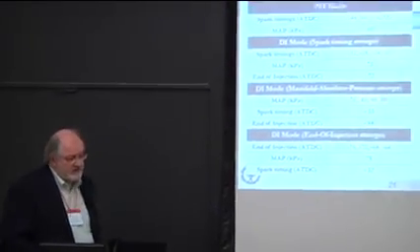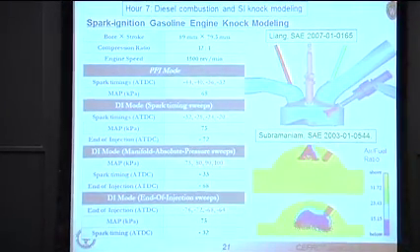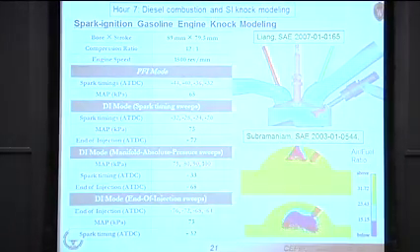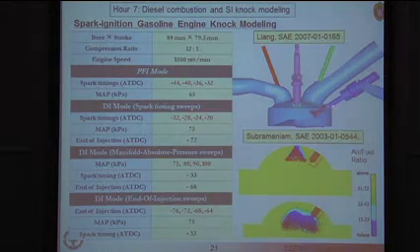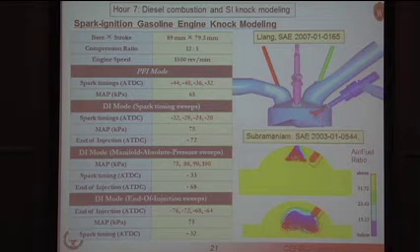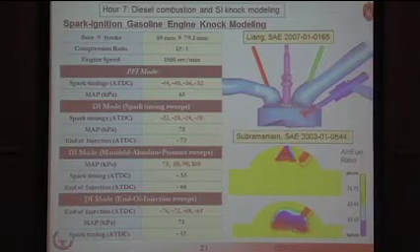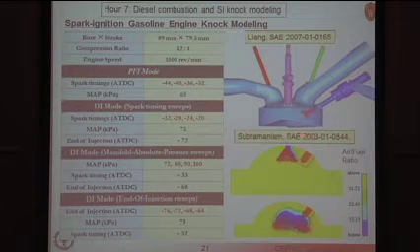And what I want to talk about now, briefly, is spark ignition engines, because spark ignition engines are also premixed combustion when we have port fuel injection, but stratified combustion when we have direct injection, like in the examples shown here. So here's your spark plug, here's your fuel injector, you inject fuel. Sometimes it's redirected by the piston geometry. Sometimes you spray directly at a spark plug. In other cases, you use the piston to move the fuel to the spark plug. These are the so-called spray-guided and wall-guided configurations.